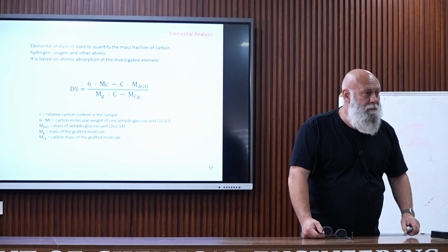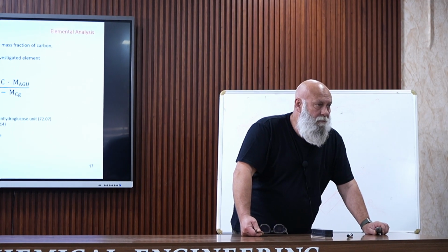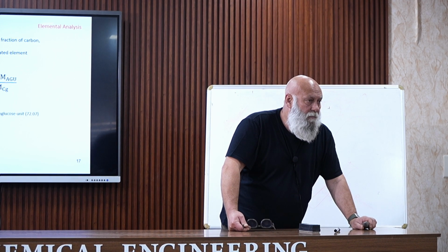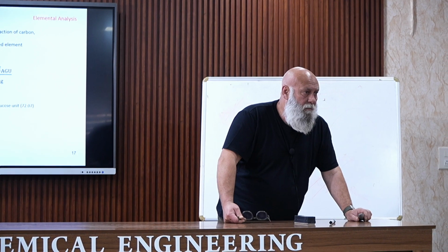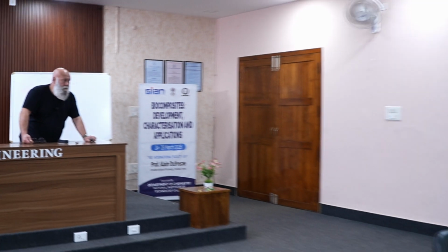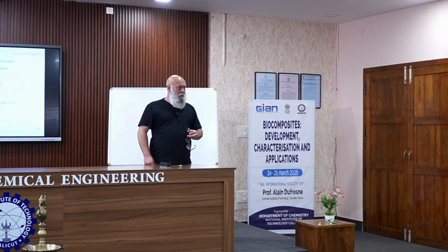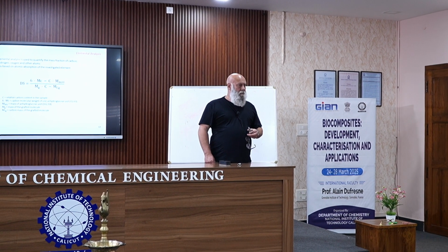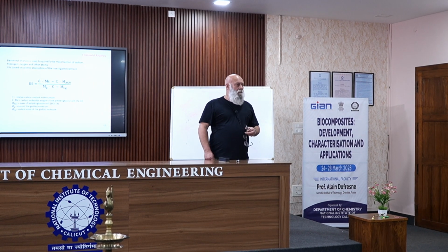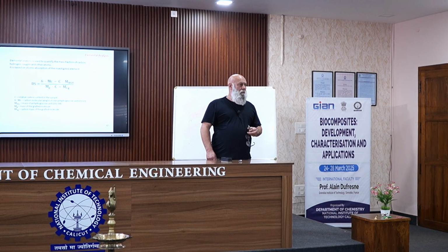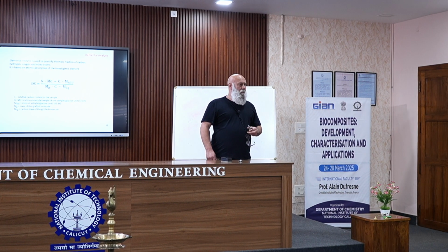Yes, sorry. Normally grafting enhances the interfacial tension because at the interface there will be more anchoring between the substrate and the cellulose fibers. So what are the strategies to evaluate the interfacial strength after doing a grafting protocol? What do you mean by the interfacial structure? The cellulose surface is grafted. Yes. So that most probably may be introducing more polar groups, and that will be getting anchored onto the polymer so that the binding between the polymer and the cellulose is elevated.